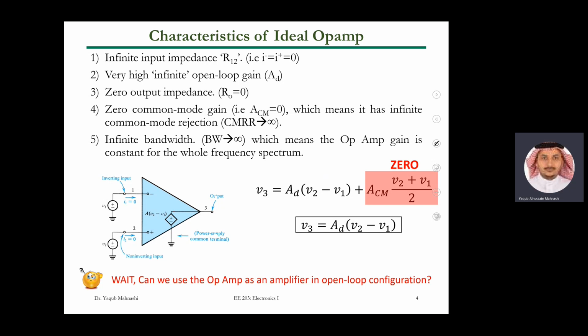And this is not practical as well, because we have some other thing we call offset voltage. Imagine you have some microvolts difference between them. Even in microvolts, yeah, there is some voltage you can see. But yeah, it's not that practical. So usually we use what we call an instrumentation amplifier. This will come later, inshallah. I'm trying to link things together somehow. But anyway, we usually use the open loop configuration like this to compare.